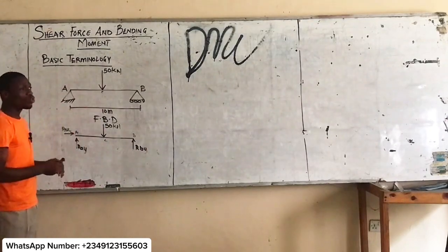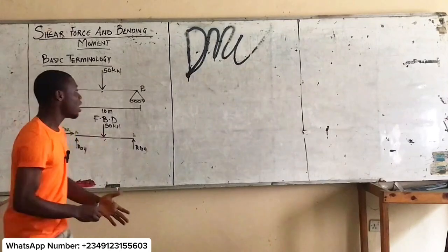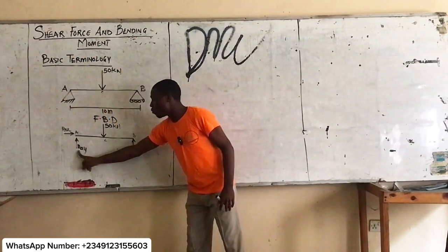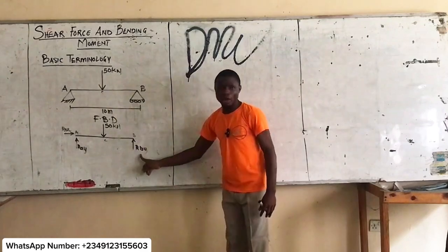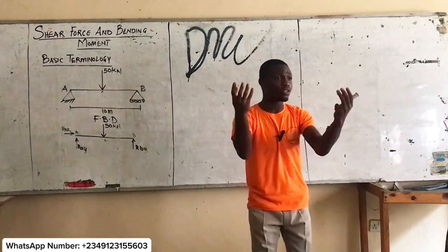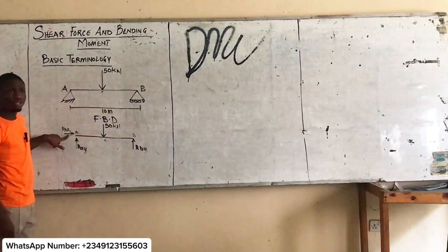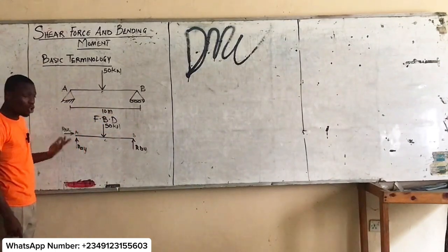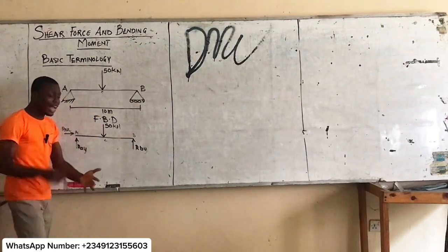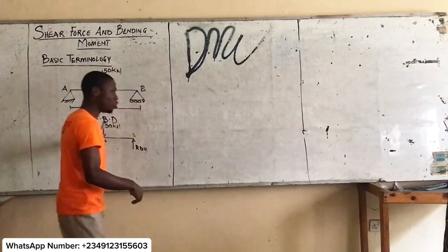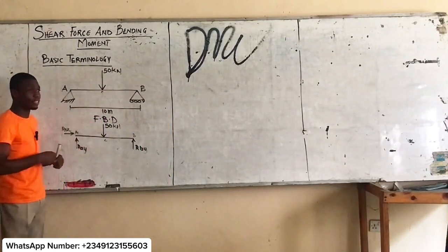So now, for me to access the drawing of the shape of the element, I need to look for RAY and RBY. Why? Because I know that these carry the load. It is not carrying any load. So these are the two that carry the load. I need to know their force for carrying this load, which we know already.